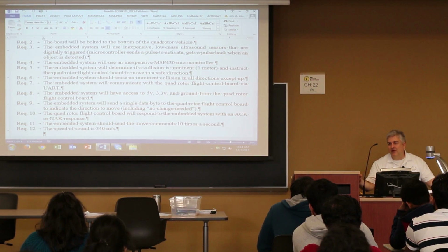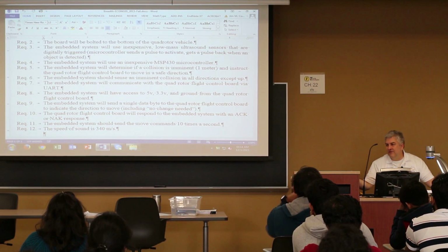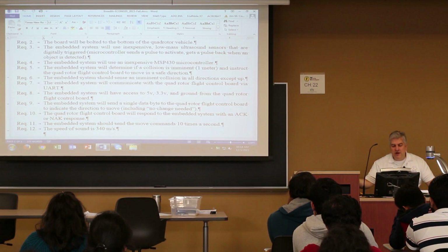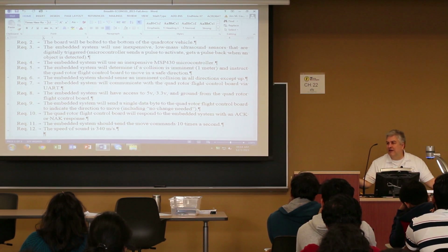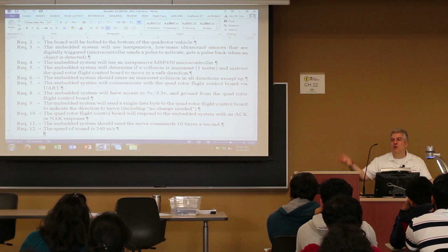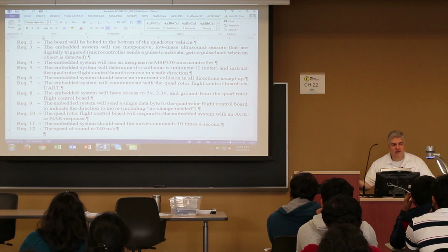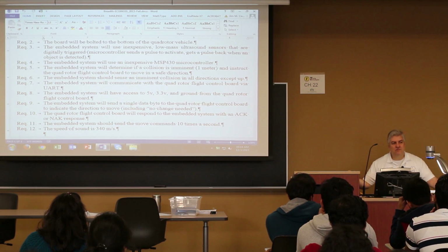So ultrasonic is a chirp that goes out and comes back. It's at such a high frequency you can't hear it, but you know that it's going to run at 340 meters per second. Per second means time. It means you need a timer to record how long that is. Now, a clever person would say, I would just let it chirp and then wait for it to come back.